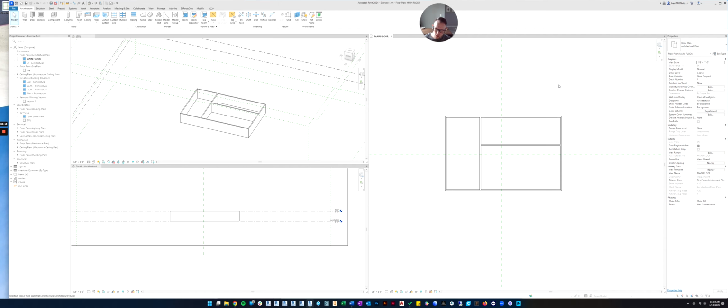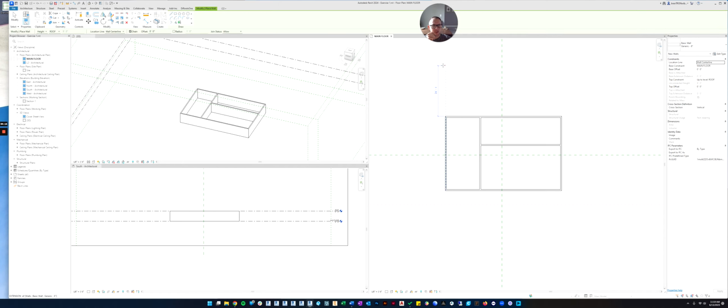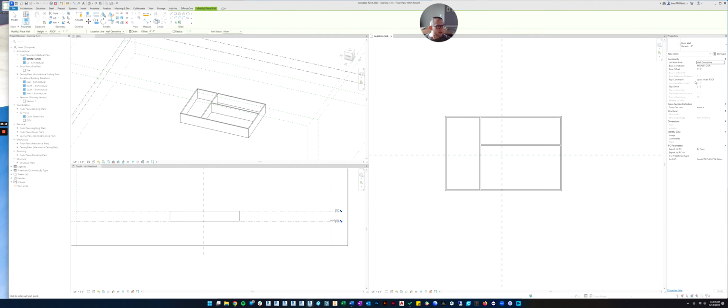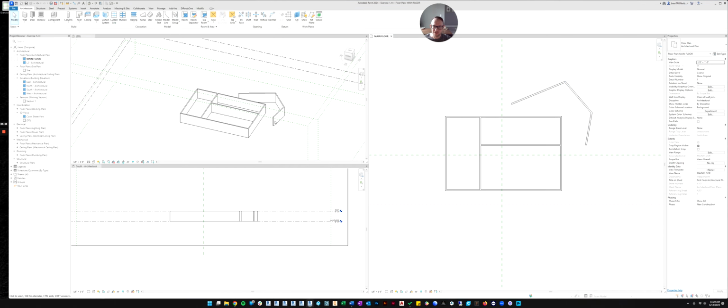So it's important when you go to draw a wall, like when I click to draw a new wall, it also remembers what your last settings were. So now I don't have to keep thinking about it. If I set these up once before I draw, it will remember the settings from now on. So now it remembers that I want to draw from the main floor up to the roof, and now I can just draw new walls without having to think.